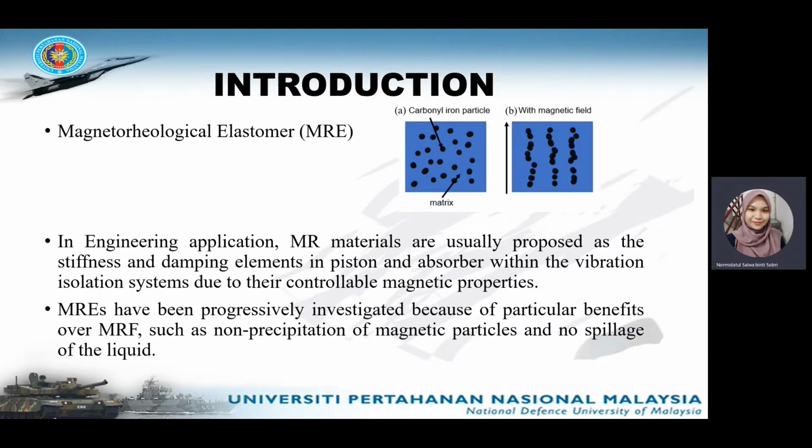In engineering application, MR materials are usually proposed as the stiffness and damping elements in piston and absorber within the vibration isolation systems due to their controllable magnetic properties. MREs have been progressively investigated because of particular benefits over MRF, which is magnetorheological fluid, such as non-precipitation of magnetic particles and no spillage of the liquid.